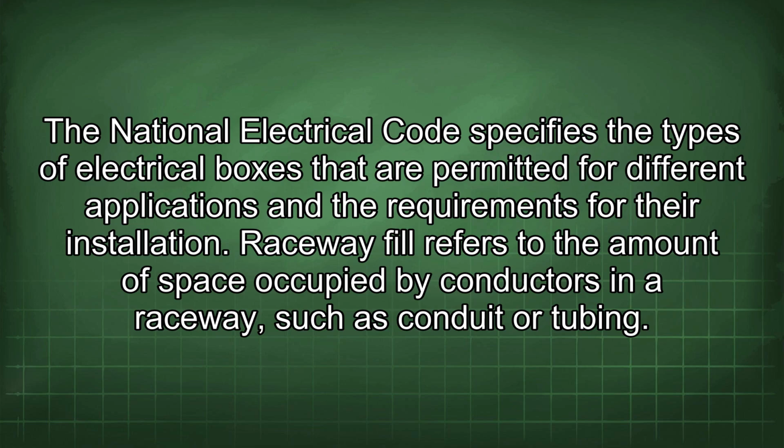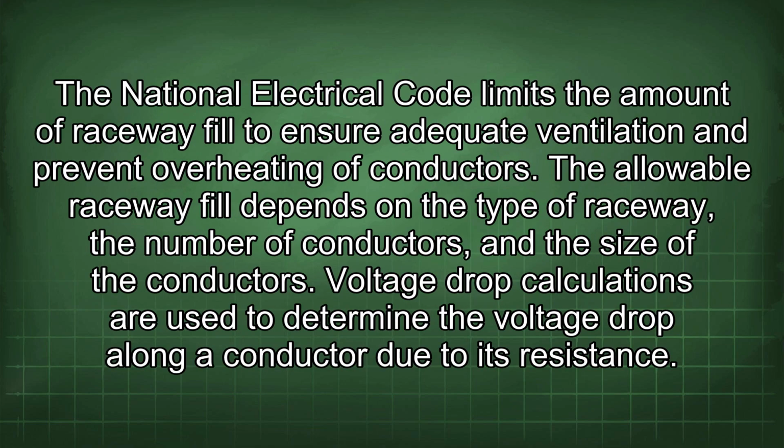Raceway fill refers to the amount of space occupied by conductors in a raceway, such as conduit or tubing. The National Electrical Code limits the amount of raceway fill to ensure adequate ventilation and prevent overheating of conductors. The allowable raceway fill depends on the type of raceway, the number of conductors, and the size of the conductors.